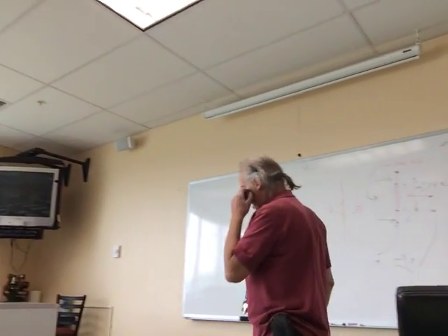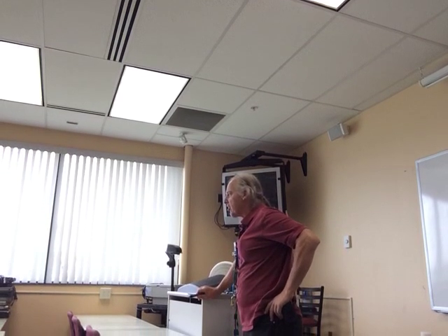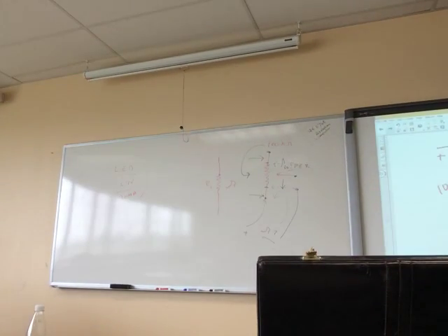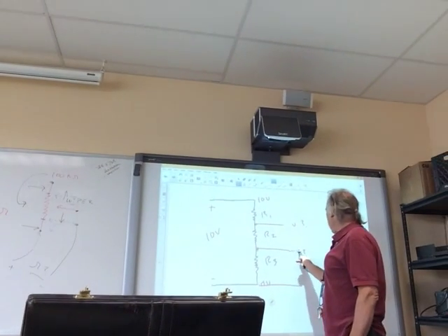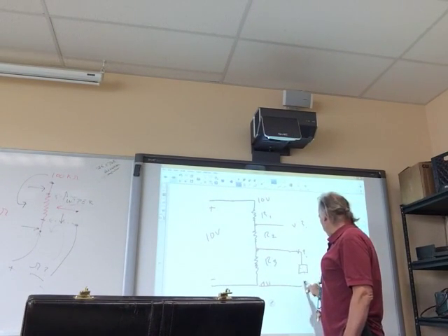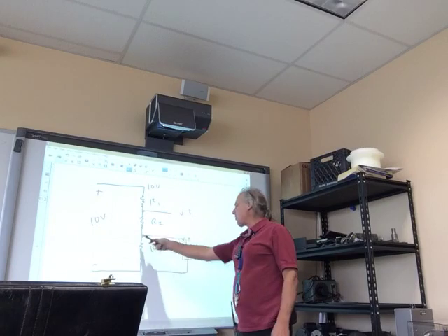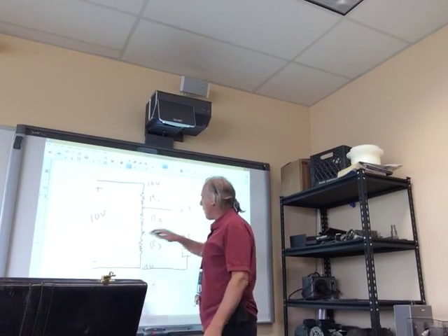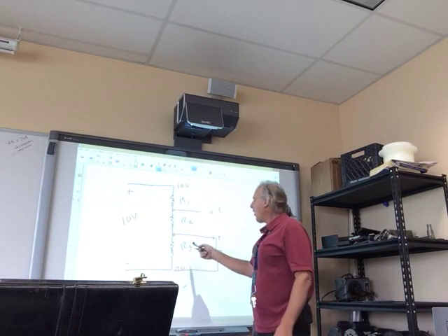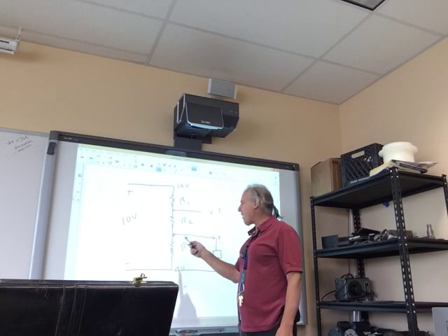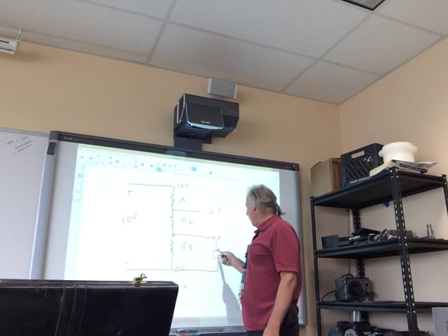Now, if I have a circuit that draws a certain amount of current, and that's all it ever draws, it's consistent, another resistor, and it never changes, then I can attach it with reference to ground. I can attach my black box, which would be a resistor in this case, okay? And it will draw a certain amount of current at a certain voltage, and this divider will be able to provide that, okay? Now, what's it going to look like here? Well, it's going to look parallel to that resistor, isn't it? So I'm going to have to make sure I pick resistors that will allow this.